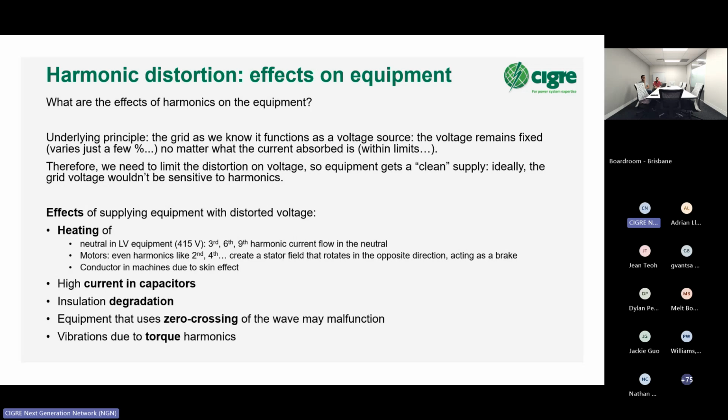So you inject current at 250 Hertz. Do you find a voltage at 250 Hertz? No, because it is a voltage source at 250 Hertz with zero voltage. It's a short circuit. No matter how much current you put in at that frequency, you will see no voltage. Why? So that the voltage remains clean for everyone. That is the objective, ideally.